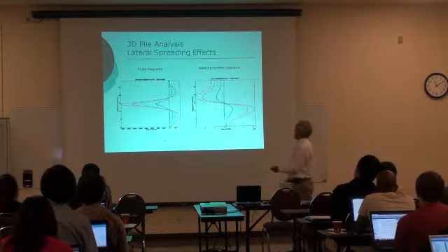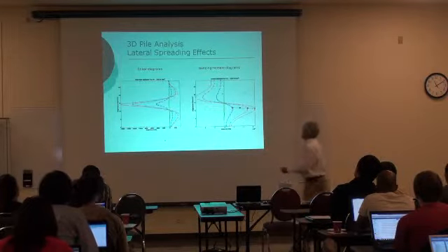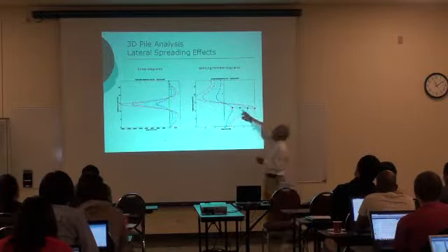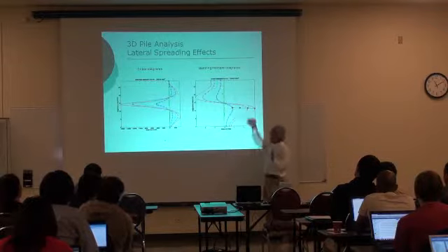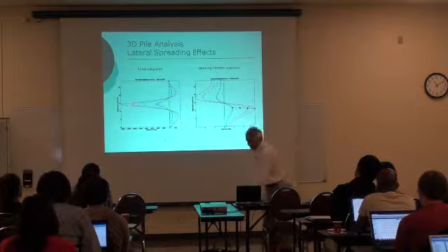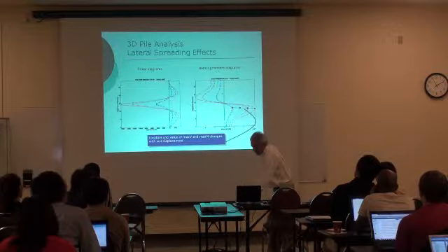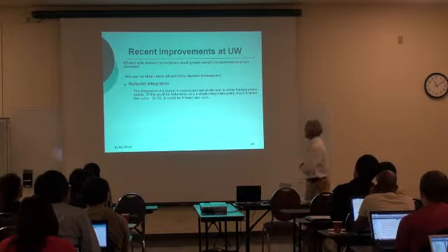You can also look at shear diagrams and bending moment diagrams, and you can see how large the maximum bending moment is for different deformations, and where the maximum bending moment is. Another thing Caltrans is interested in knowing is how large the bending moments are and the location of the maximum bending moments. So that's another thing that we could do using this.